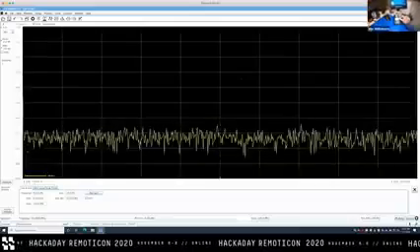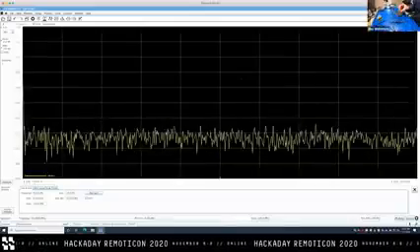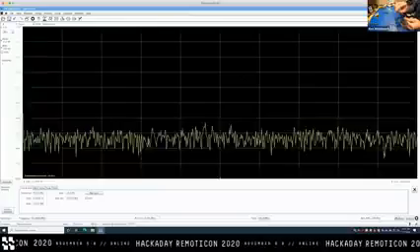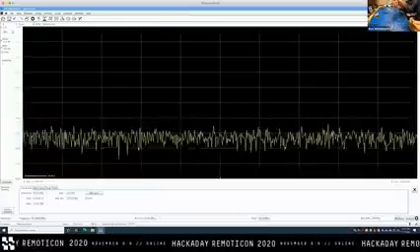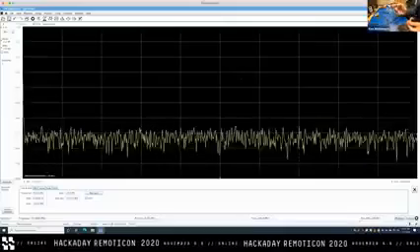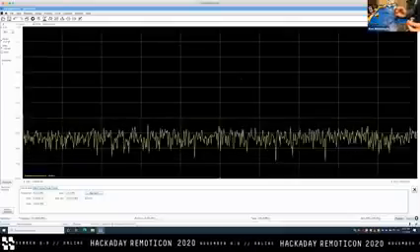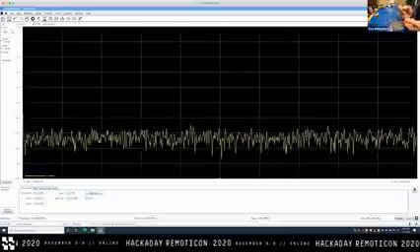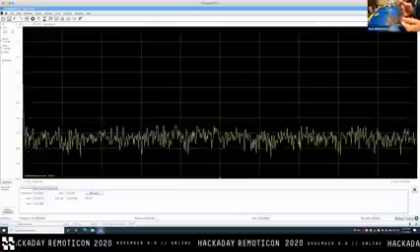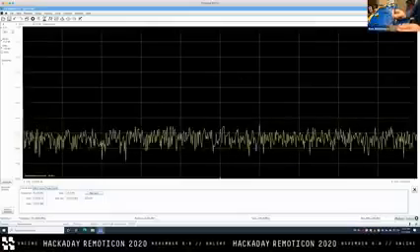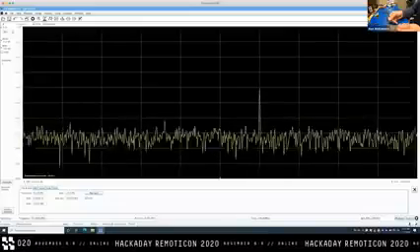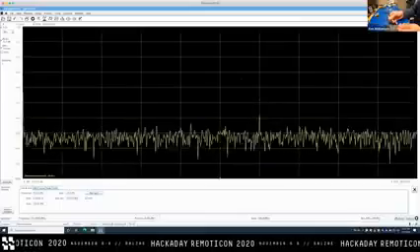And okay, what's going on over here? That's a little odd. Let's dig in on that a little bit before we get too much farther. I'm going to switch to this tiny little H-field probe. If this looks similar, for those of you who followed along at home to begin with the really small DIY probe you might have already made, the whole point of this probe is that it's the same magnetic loop antenna, but in a tiny little package up at that tip. So we should be able to see, if we wander around with the loop parallel to the board, that 60 megahertz seems to be over here, and it's not actually over here anywhere out in the free space.